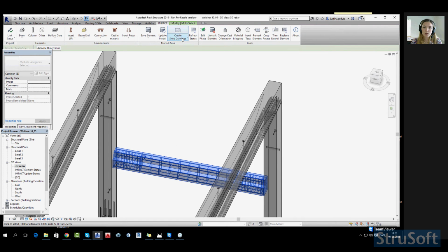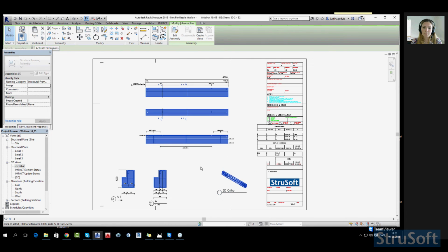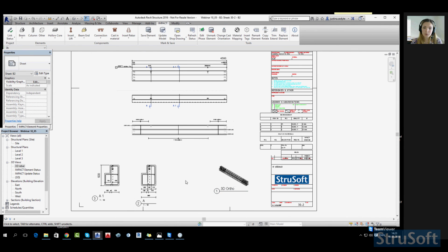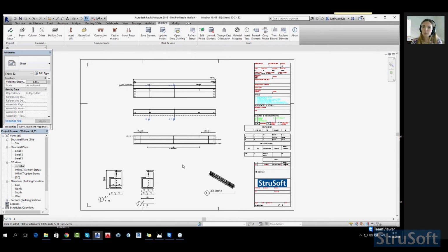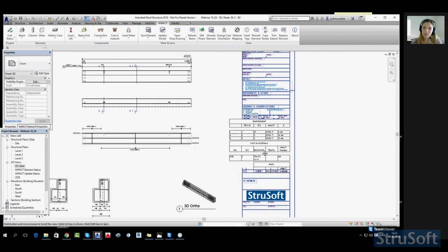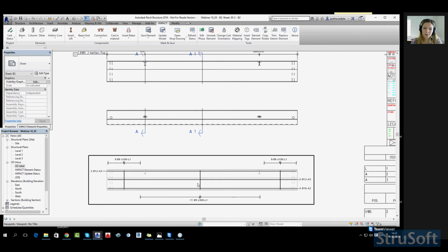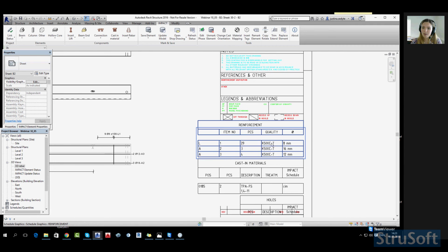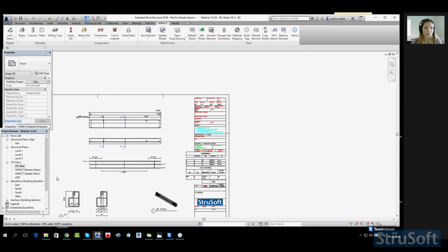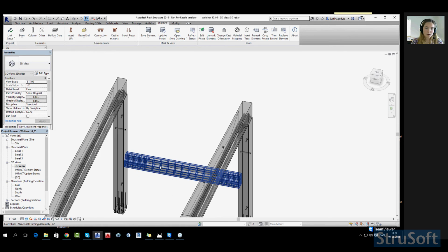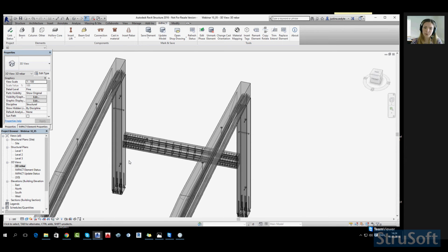Okay, now I have the drawing done. I can simply browse it in a project browser, but the fastest option is just simply go and open shop drawing. Now you see we have 3D preview, we have sections that we can also set in, and as I said, this program is totally adjustable to your company standards. You can have your own schedules, reinforcement schedules, casting materials, other information regarding project. So now I have those marked reinforcement bars and the schedule. Okay, it seems to be fine.